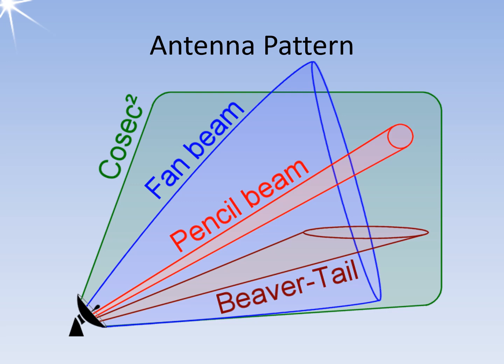To generate the most efficient spatial scanning pattern for a 2D radar, a cosecant squared pattern can be produced by modifying the reflector of a parabolic antenna. For short-range air traffic control radars, waveguide slot antennas are commonly used. However, they typically only generate a fan beam pattern.